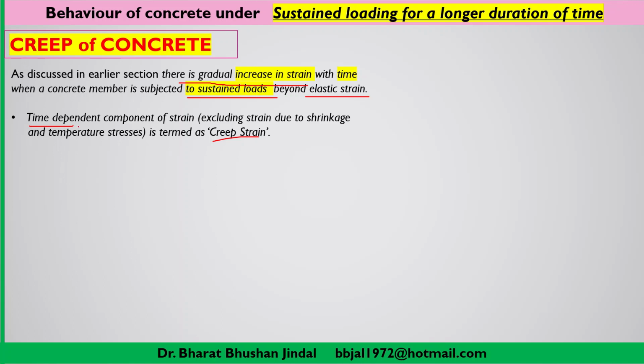So the time dependent component of the strain, where we will be including the strain due to shrinkage as well as temperature stresses. So when you exclude the strain due to shrinkage and temperature stresses, that type of strain which is time dependent, that means it depends on the duration, is known as creep strain. So it is very much clear that creep is a form of strain.